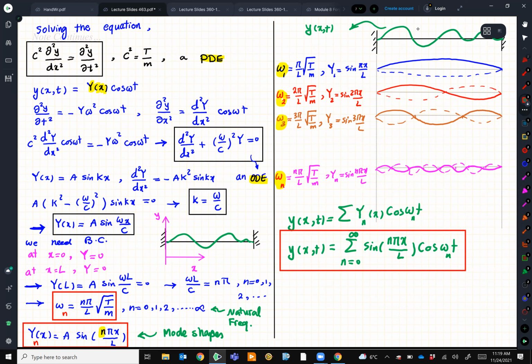Based on that, obviously, you can find the tension in the string, because if you know omega_n, simply you can find T. And as you can see, you can change the natural frequency of this system, the string, by changing the tension. And the A factor here is the scaling factor. It depends on initially how much we displace the whole thing. It can be twice or 3 times, doesn't matter.